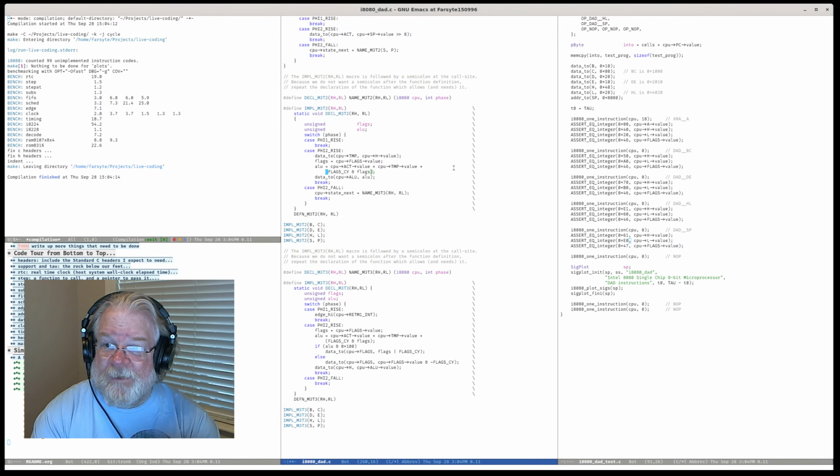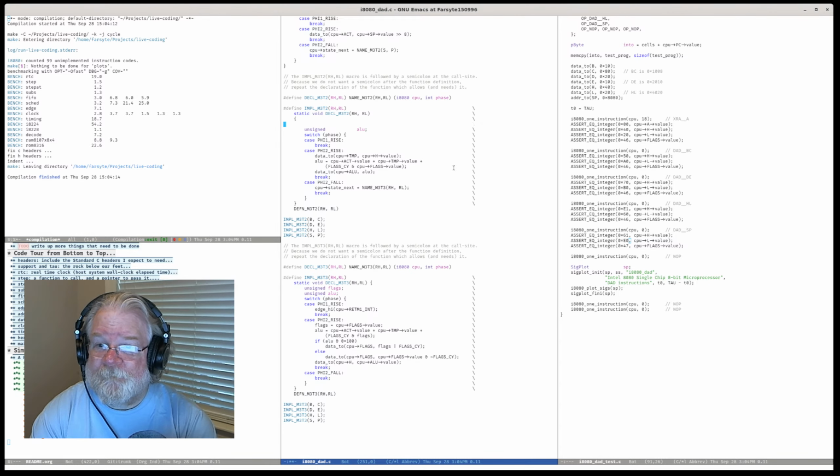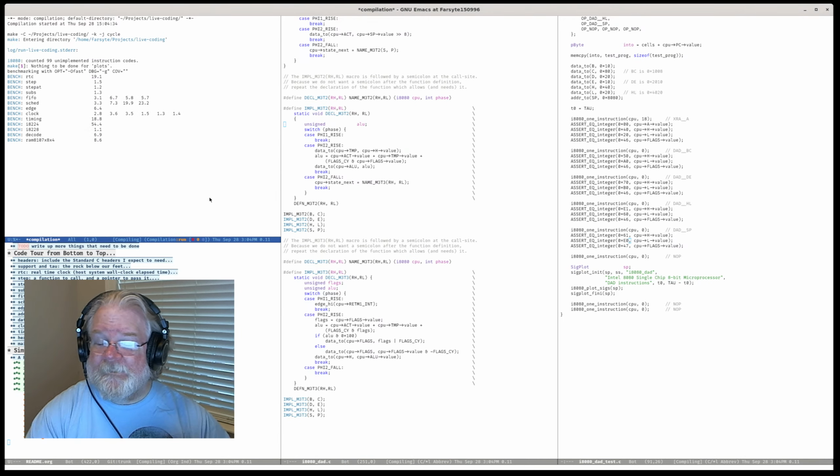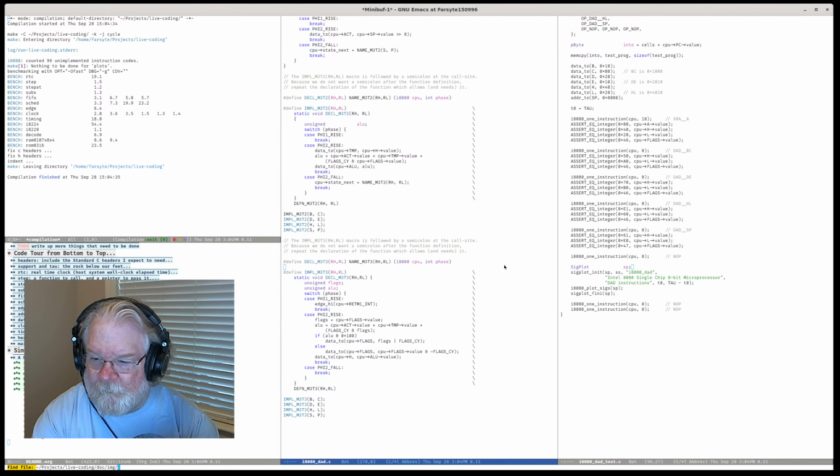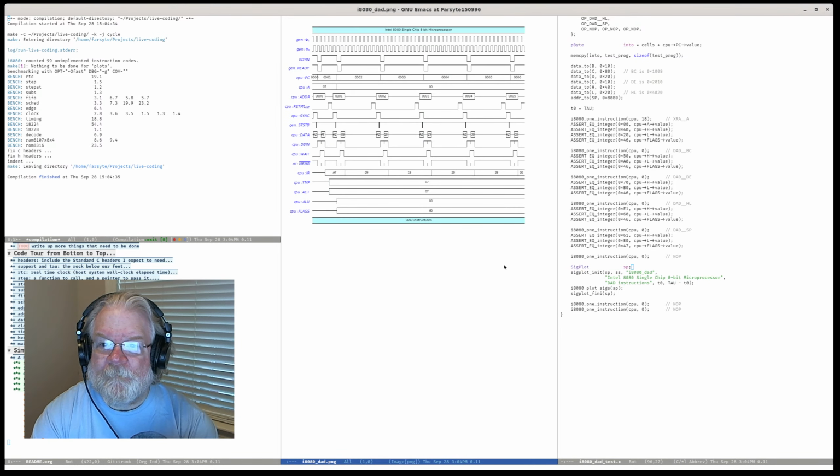So now we're checking also that the carry flag is handled here. And I'm going to eliminate the flag variable from there. So there's DAD. Let's take a look at the plot. So this is our double add test. We start with valid data in BC, DE, HL, SP, which is all set before we start the plot, so that it doesn't show here.